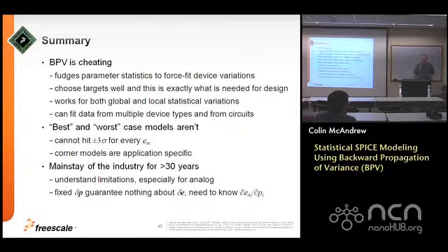Yeah, so the answer is no. When I've found that situation, it's generally because there's a problem in the extraction of the SPICE model parameters. Often it'll be like VT as a function of L is doing this, and then it goes off a cliff. So what'll happen is, if you put in too large a variation, all hell breaks loose from that. And what we do then is basically go back and fix up the SPICE model from which we get the sensitivity. The reason for doing that is that if any designer hits that in practice, it's going to be a disaster anyway, so we fix that model up.